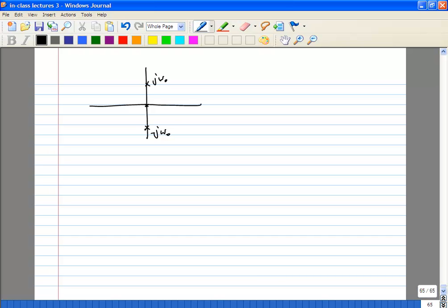So what happens is, initially the poles start off somewhere here in these two places, right? One of them is a capacitor, the other is an inductor. Eventually they will move somewhere here, and you will see them splitting. This is your Q equals half point. If you take your discriminant, root of b squared minus 4ac, you'll find that at that point it goes negative, and you can get the condition Q equals half from there.